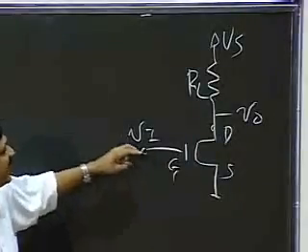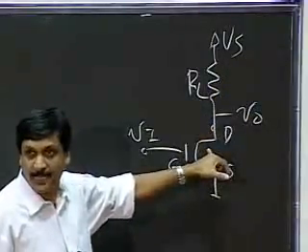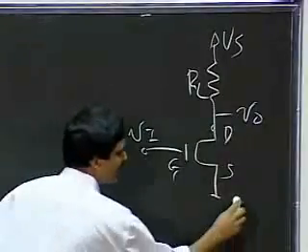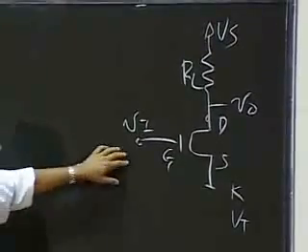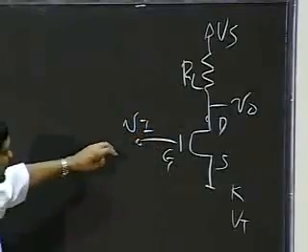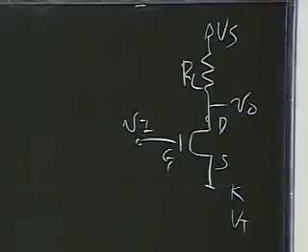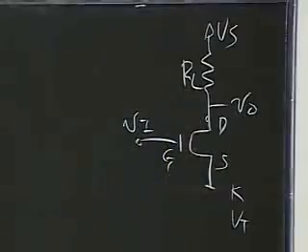What I'm looking to do is that given a value of the supply Vs, RL, and a MOSFET, in our case, given a MOSFET implies that there's a given value of K and a given value of Vt for that MOSFET. So let's assume Vi is my free variable here. My goal will be to find out the range of Vi for which this device stays in saturation. Okay? And I'll use both a combination of a graphical method to give you intuition and then apply analytical analysis to get down to specific answers.